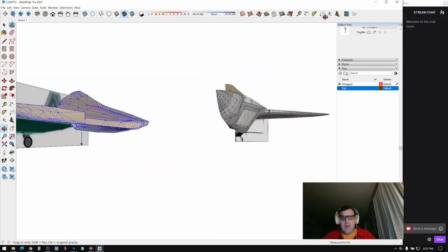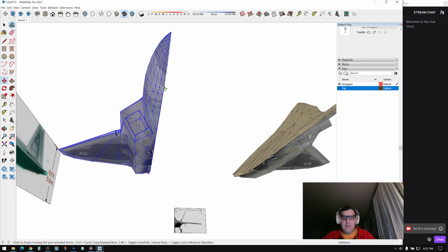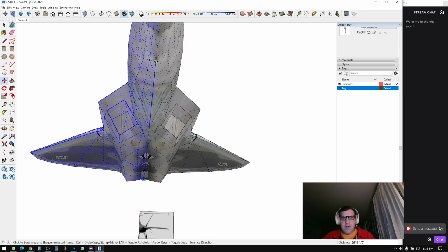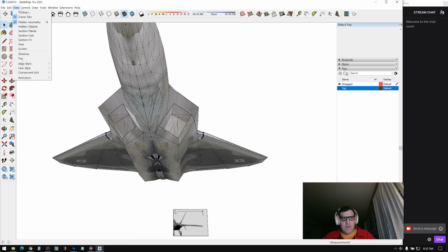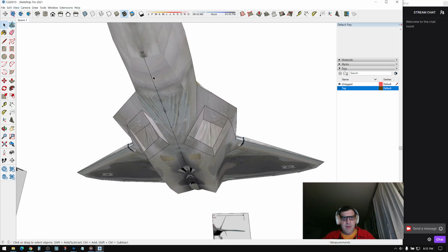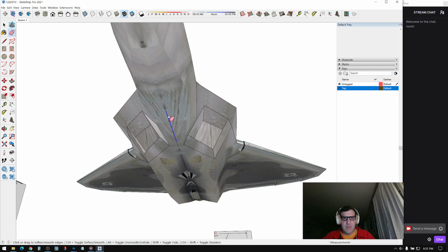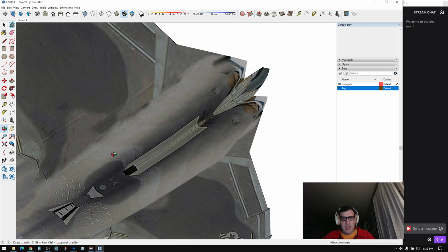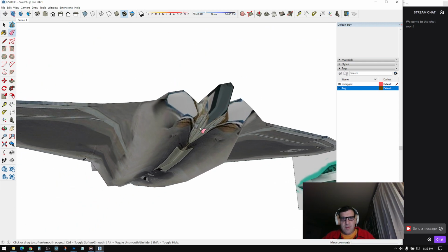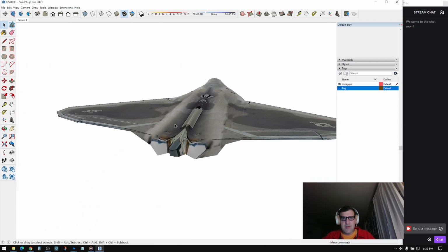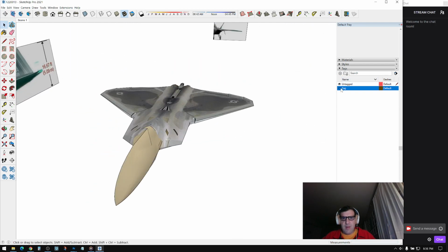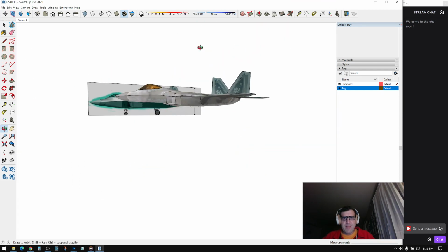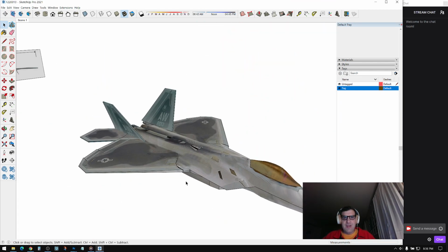Okay, now we'll move it back over and snap it to where it goes there. Turn off view hidden geometry, and then just smooth out the rest of these lines in the middle holding Control and using the eraser tool. It's a very nice, handy little trick. Then I turn that tag back on, we get our meshes back. Back in business.